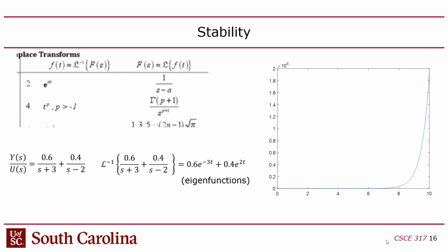And then if you plot this, this is the impulse response, but in the time domain. So if the input to this were an impulse, like you hit it, the output goes up infinitely, right? It's unbounded, right? That makes sense? Now you might say, well, aren't they all just going to look like that? It's just an exponential. Yeah, but you can see when it happens at 8 seconds. Basically at 8 seconds is when you get the elbow of that curve and it shoots up, right?